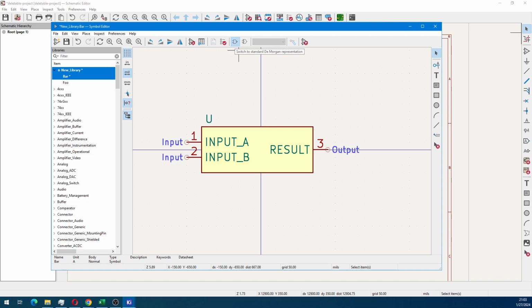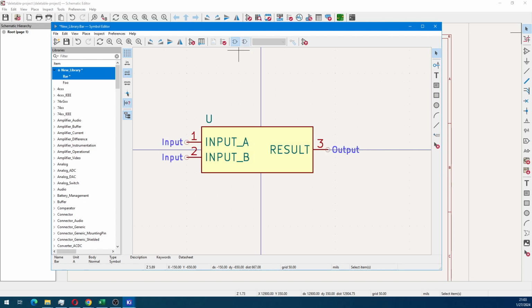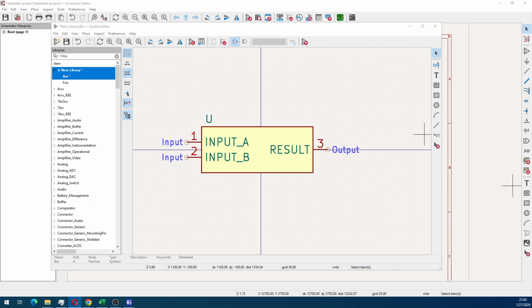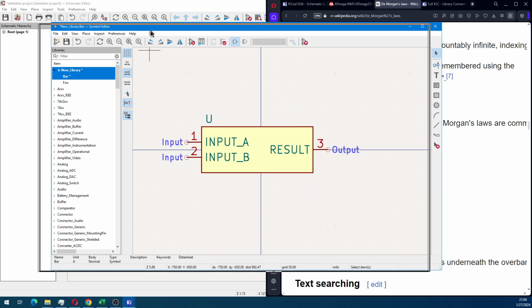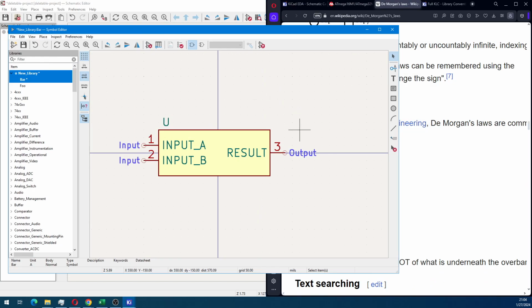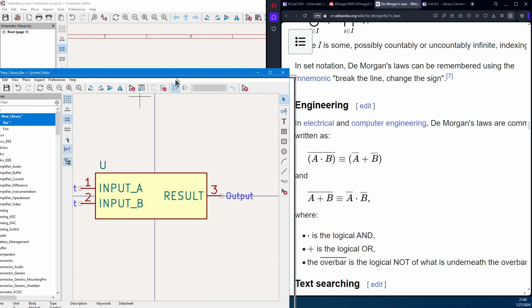So in Boolean algebra, maybe to back up, if you're designing combinational logic, like maybe for an FPGA, and you're trying to figure out your circuit in Boolean algebra, you have this property of DeMorgan's law, and especially when you're making decoders, it can simplify your logic and give you an opportunity to reduce the number of gates.